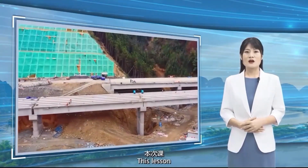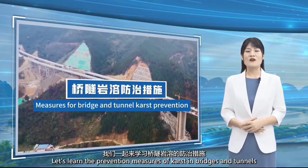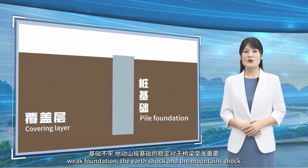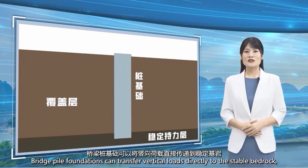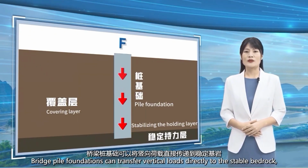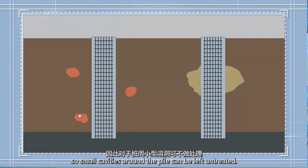In this lesson, we will learn about the prevention and control measures for karst in bridges and tunnels. The stability of the foundation is the key for bridges. Bridge pile foundations can transfer vertical loads directly to the stable bedrock, so small cavities around the pile can be left untreated.